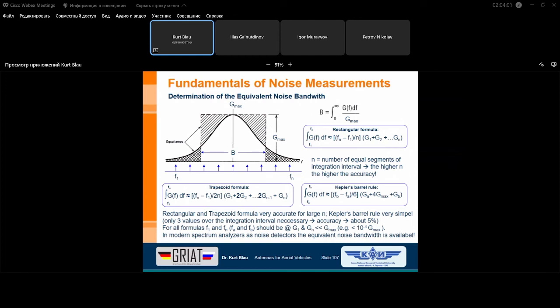What you can do in practice is make a galvanic skin finish from silver. Then you can save this very expensive material and increase the conductivity. But silver has the disadvantage that it reacts with some materials in the air if the antenna is mounted outside and not under a radome.